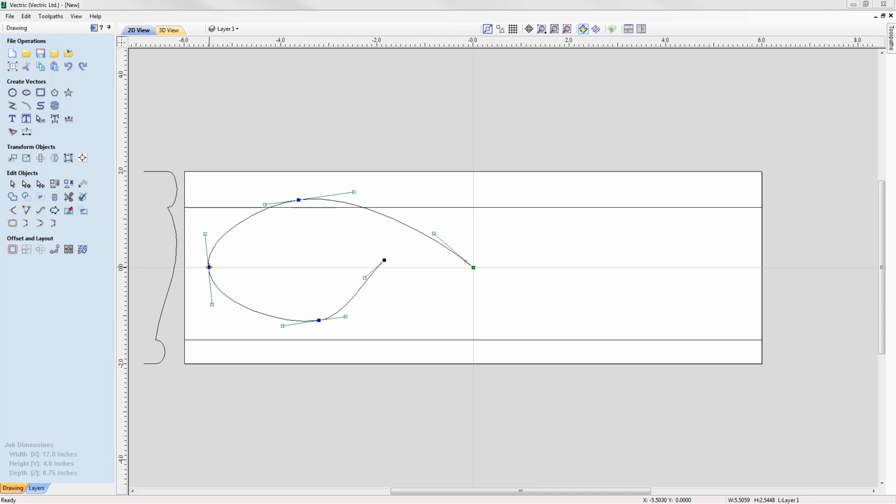Now, tip here is if you select the node, you'll notice that the control handles are also selected. And if you wanted to line them up so they all line up in the x-axis against the original node, just simply press X on the keyboard and you see that it keeps everything in line there. And then here I could just select this handle, I could maybe nudge it up a little bit using the up arrow key. I could also take the span and just move that over,